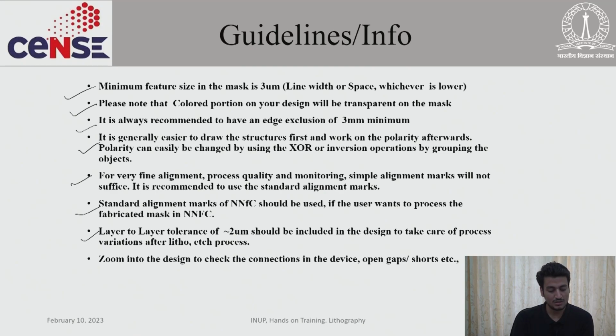The next one is to zoom into the design to check the connections in the device design, open gaps and shorts, etc. This is a very important point, because after designing in the software there might be some voids or some extra lines, since we use a lot of operations on our device geometries. Suppose you make a device using 3 or 4 different kinds of geometries and apply an operation like XOR. After the operation there might be some line residue or some void creation.